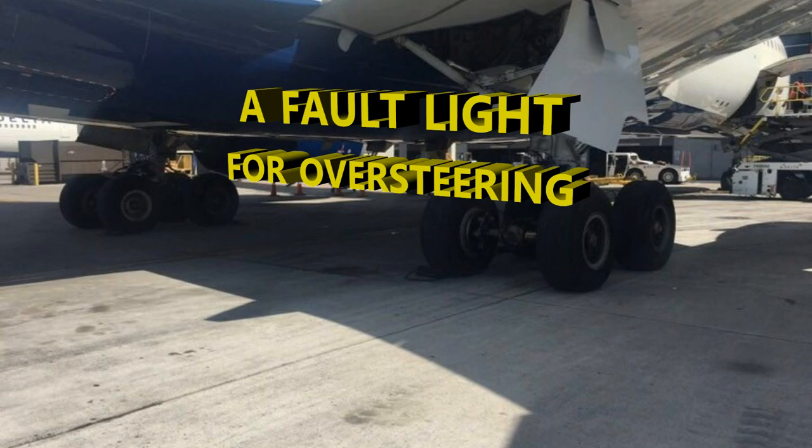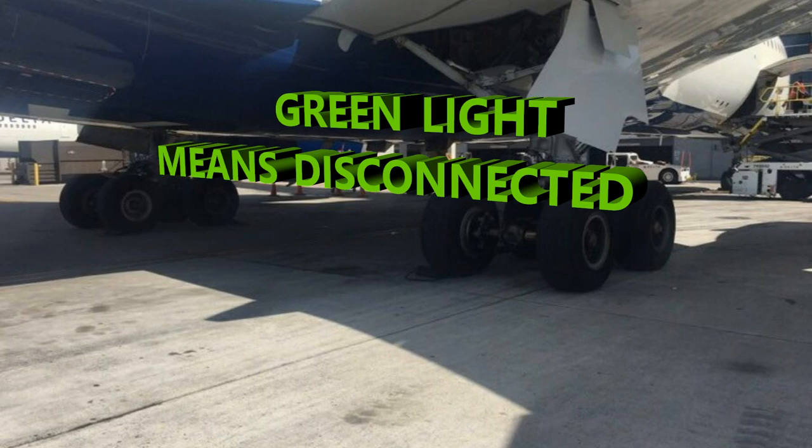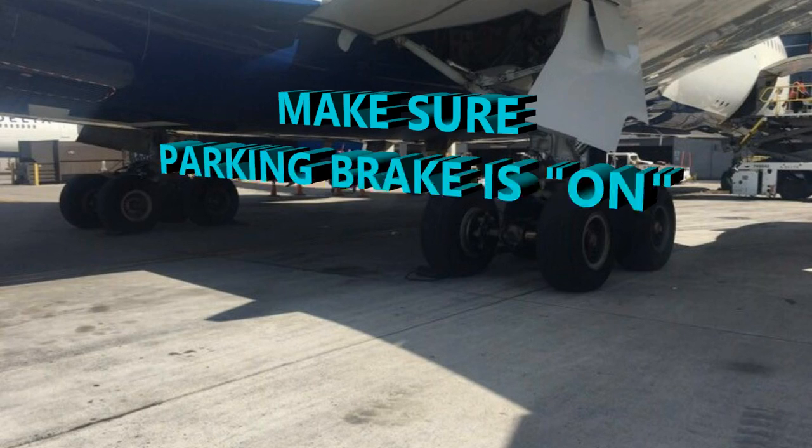You'll see on the steering disconnect panel there's a steering warning that'll be showing in an amber colored light. Green means you have a disconnect, in other words just what you want, and that's a good thing, because that's the whole idea of the disconnect panel. One of the things to be aware of is, before you do any of this, you want to make sure that the aircraft is in park, as in the park is on, in the on position.